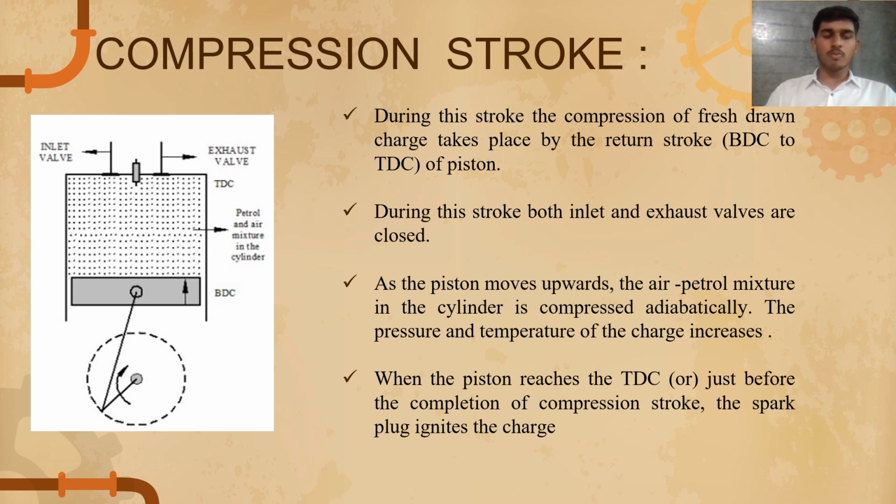As the piston moves upwards, the air and petrol mixture in the cylinder is compressed adiabatically. The pressure and temperature of the charges increases. When the piston reaches the top dead center or just before the completion of the compression stroke, the spark plug which is inserted in the cylinder head ignites the charges.